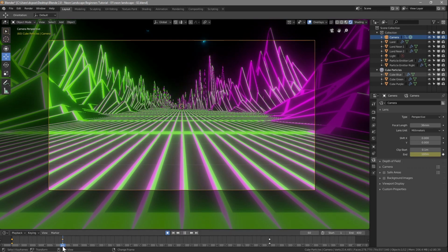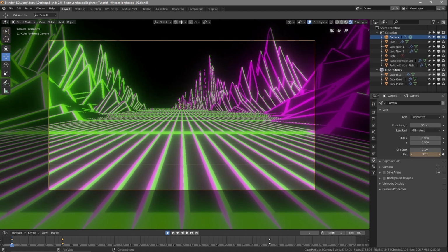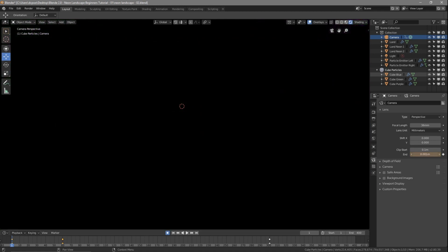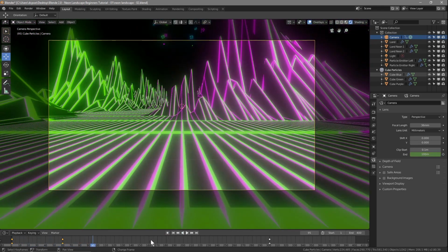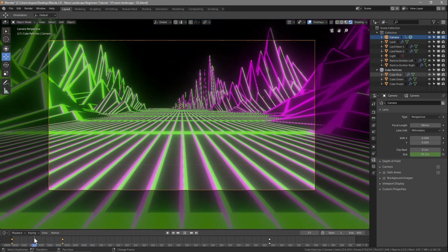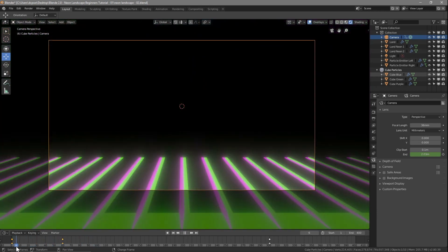So we want to go back to the first frame and set the camera clip all the way down to 0. Let's set it to 0, and it was this number here. Just click on it and type in 0. Then we can untick the record button and click play, and now our scene will get built before the camera moves. Because really all we're doing is saying to the camera, how far can you see into the distance?